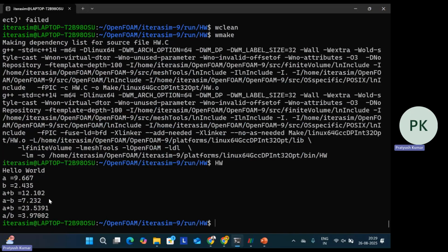For that we need to inform the audience that these are the parameters that are relevant. Let's say a drop is falling from cloud to the ground in the rainy season. If someone is interested in simulating the falling of a droplet, then you can track the centroid of the drop. In order to track the centroid of the drop, you need to code certain things, and this coding is required while post processing. So you can code similar things inside the .C file in C++. Is that clear?